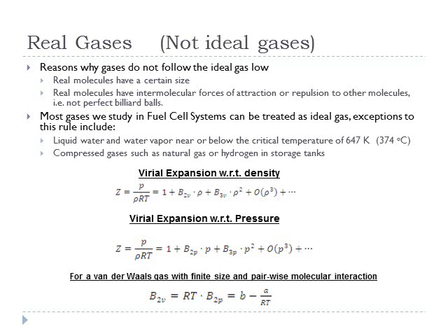Okay, the times that we can't are going to be for when there's liquid water or water vapor near or around its critical point of water, which is 647 Kelvin, 374 degrees C. So this is going to be for PEM fuel cells. Anytime you're treating systems with liquid water, you can't treat liquid water or even steam when it's in equilibrium with liquid water as an ideal gas.